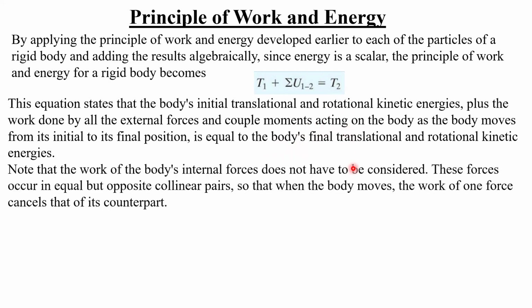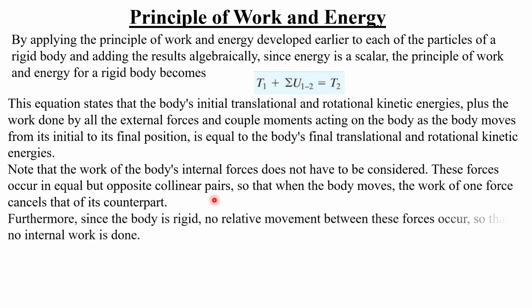Note that the work of the body's internal forces does not have to be considered. These forces occur in equal but opposite collinear pairs, so that when the body moves, the work of one force cancels that of its counterpart. Furthermore, since the body is rigid, no relative movement between these forces occurs, so that no internal work is done.